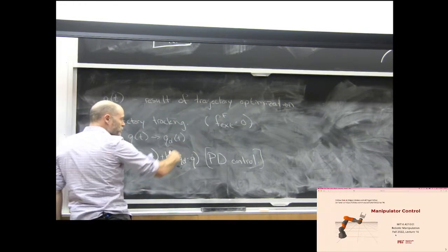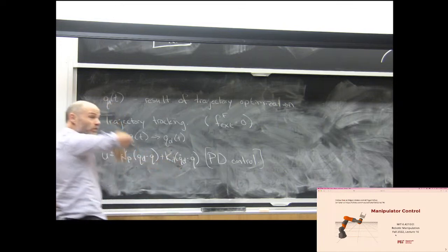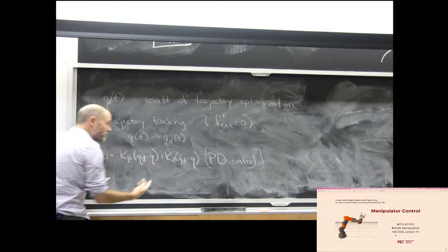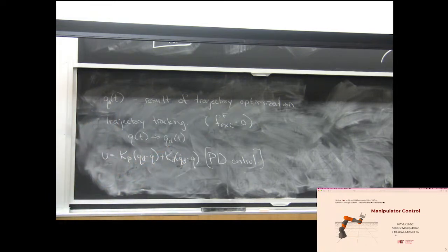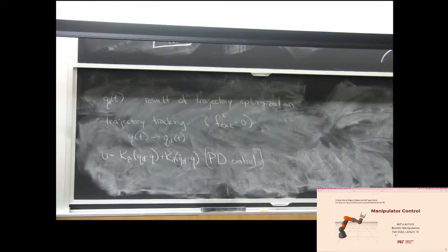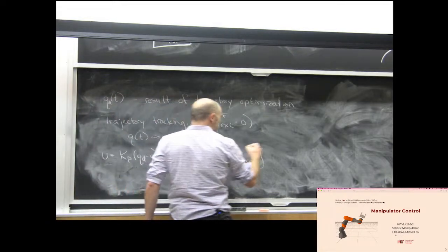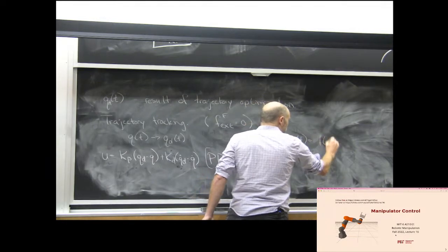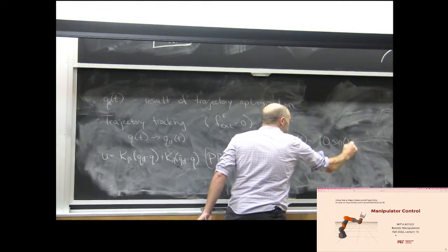By the way, this is well defined. If I have a trajectory a priori, I could take the derivative of that trajectory, and I could have a desired velocity at every instant in time too if I'm tracking some trajectory. Okay. So what happens if I put this controller even into my little mass system? Let's say I have a desired trajectory that was just a sine wave, say Q desired of t was 10 times sine of t.